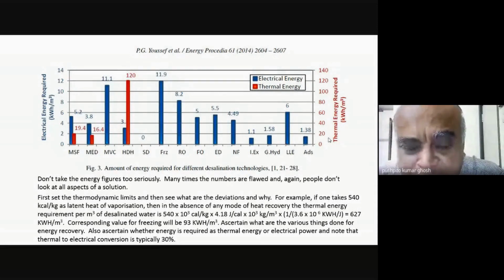Anyone would try to practice commercially the most attractive process. For example, if today the entire world has shifted to reverse osmosis, there must be a reason. So we will try and understand. But you can surely see that thermal desalination can take huge amounts of energy, unless you have got some source of waste energy, some waste heat.